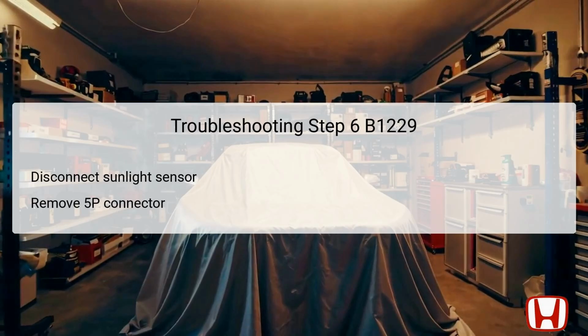Once the sunlight sensor is disconnected, it allows for individual testing and inspection, which is necessary to verify that the sunlight sensor itself is functioning properly and that the wiring leading to it is intact.